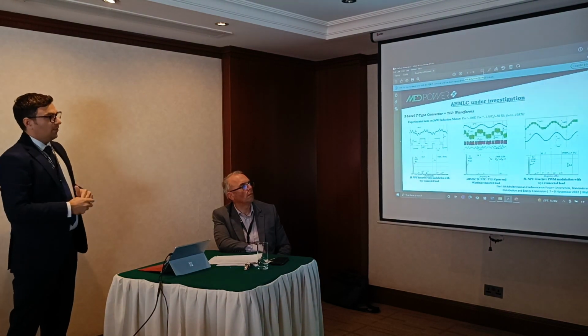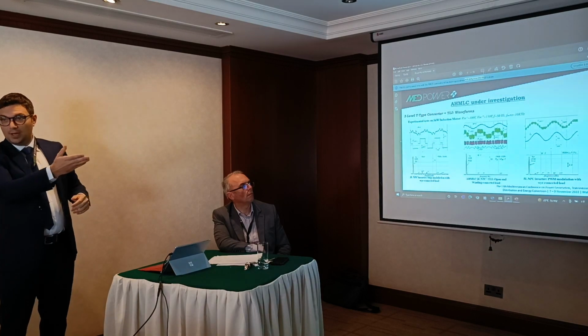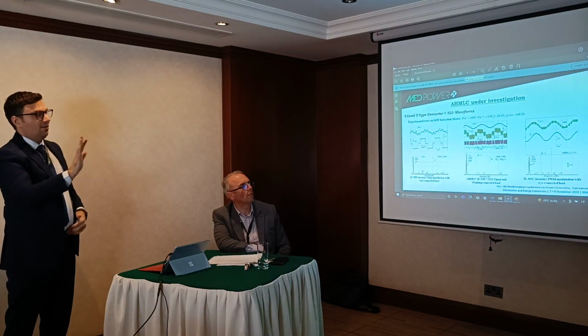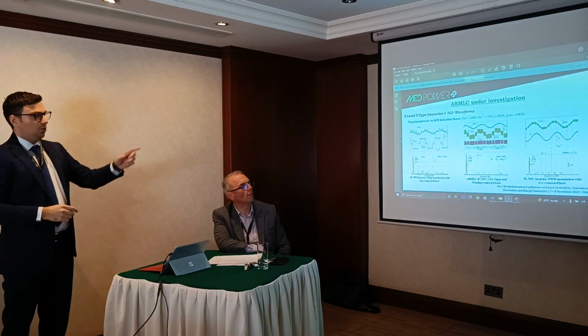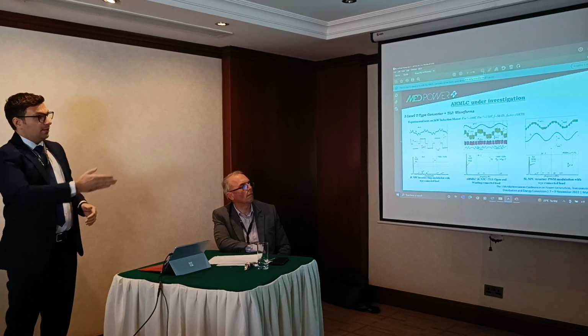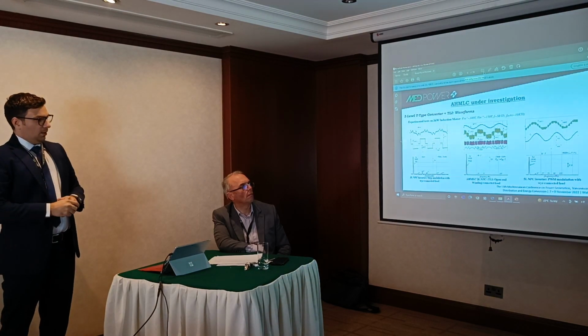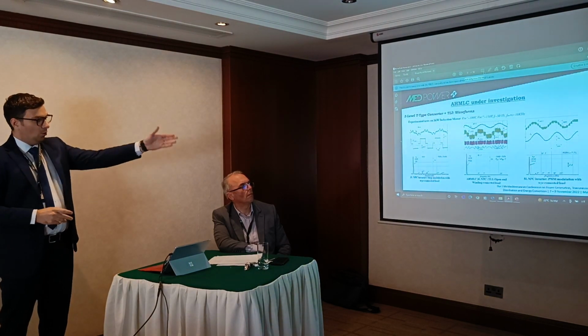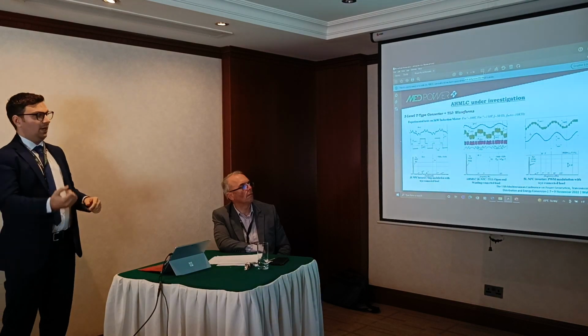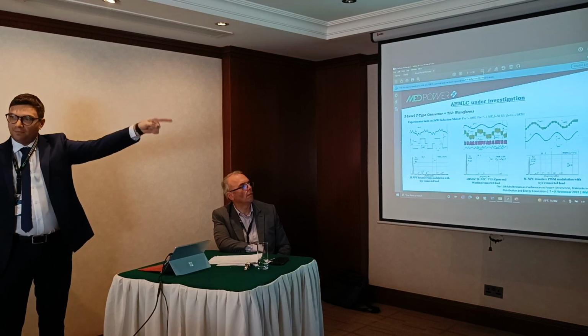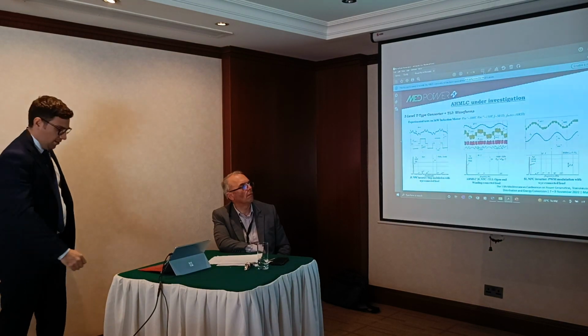In the middle, we have the proposed three-level plus active power filter, and on the right, we can see the case of five-level PWM modulation with a wye-connected load. We can see that in the middle, with the proposed configuration, we achieve a lower value of total harmonic distortion by using a smaller number of power switches compared to the five-level PWM modulated inverter.